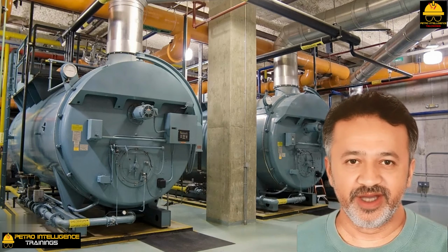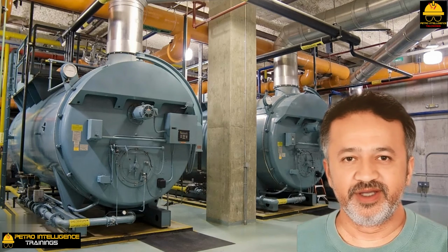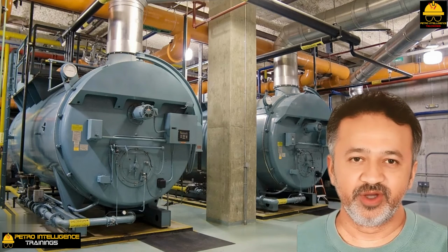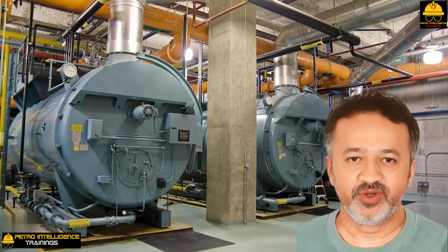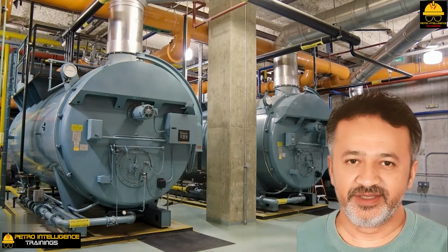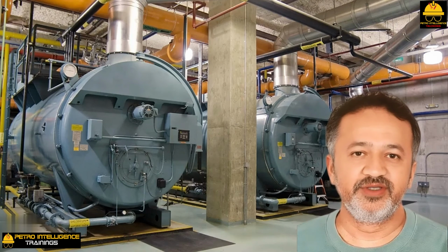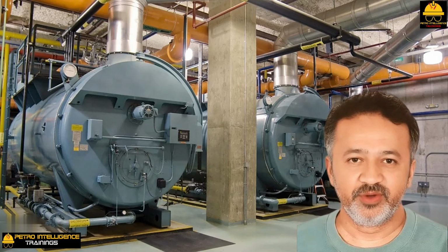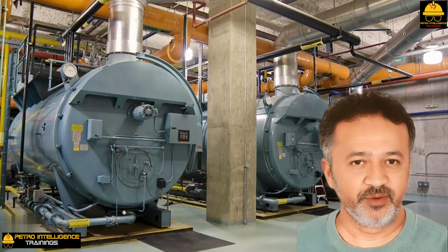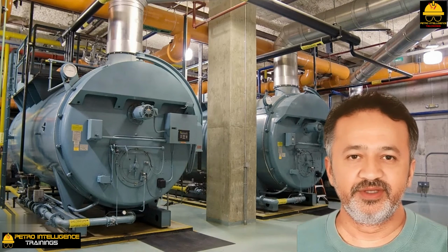Boiler feed water preheat. The optimum feed temperature to a deaerator is the boiling point of water at the deaerator pressure. Typically, 230 degrees Fahrenheit to 240 degrees Fahrenheit. However, in many plants, BFW to the deaerator is heated to 160 degrees Fahrenheit to 180 degrees Fahrenheit by heat exchange with process pump around or product streams.